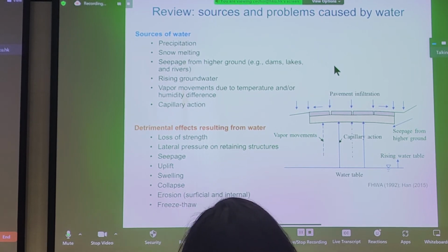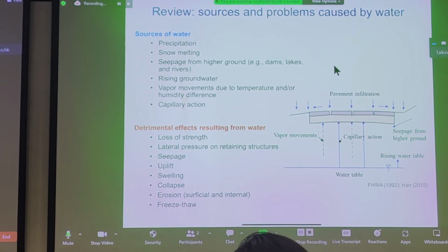It's not right to say pressure head or velocity head, it's total head. You have elevation, velocity, and pressure, right? Sometimes we just think that higher elevation controls flow, but that's not a complete answer. It's almost a trick most of the time.